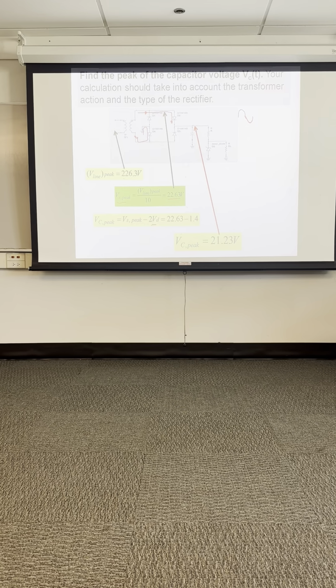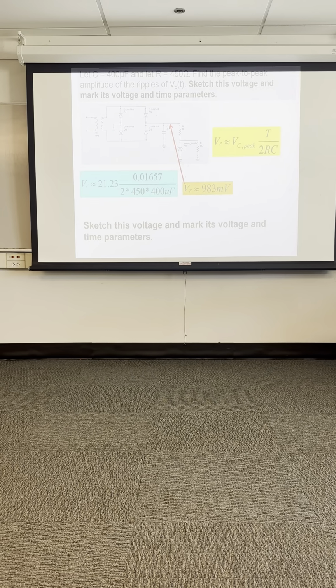Now there's also the reverse current version, which is how does it work on the reverse current. AC basically has to come back to D3, and then how does it get to this terminal here? Yes, the only path is through D1, and the only path to D1 is through ground. So it passes through ground and returns to D1. So that's how the bridge rectifier actually operates.